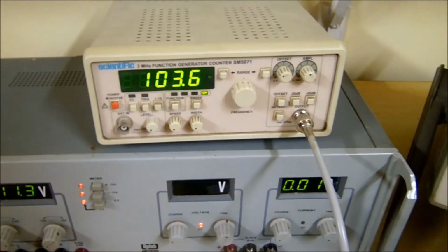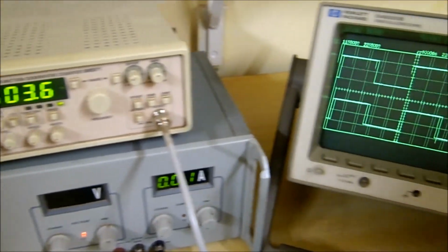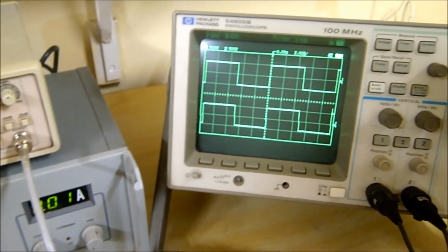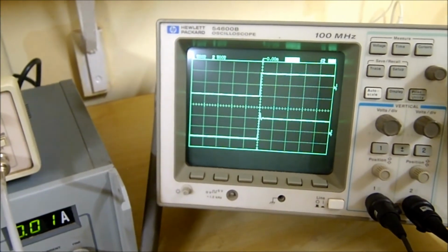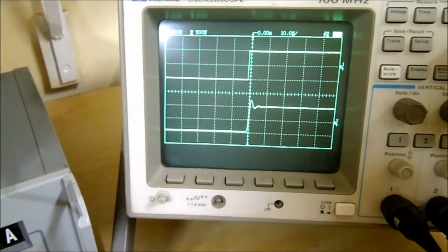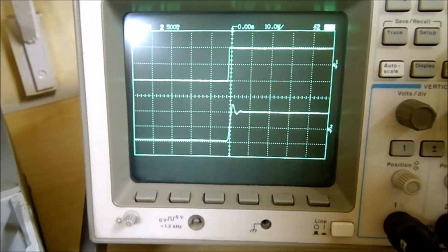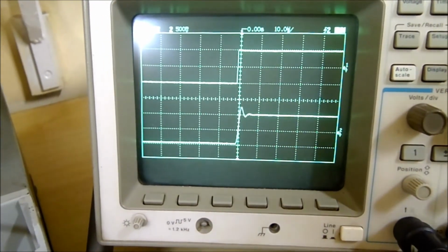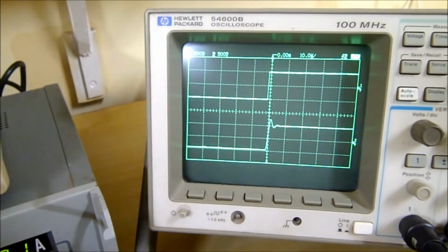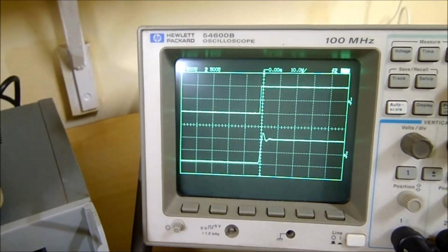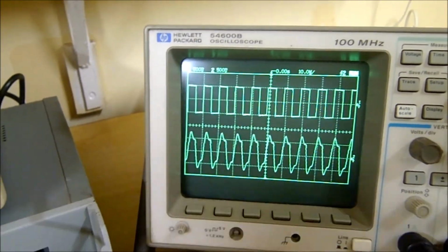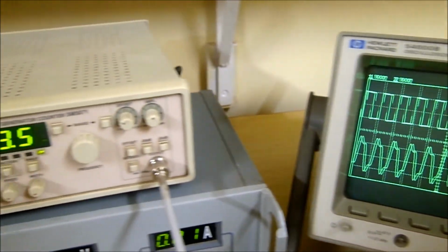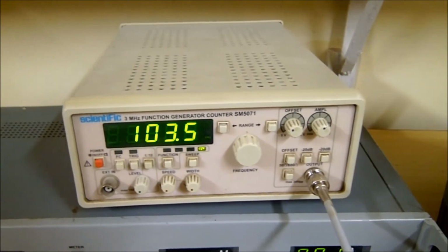For the transient response, we applied square wave of 1 volt peak to peak with frequency 100 Hz. Now to visualize the transient response properly, we had to decrease the time per division knob. As the frequency is low, we observe both the transient as well as steady state response. But as we increase the frequency, we can get only the transient response as the input voltage changes before it reaches the steady state.